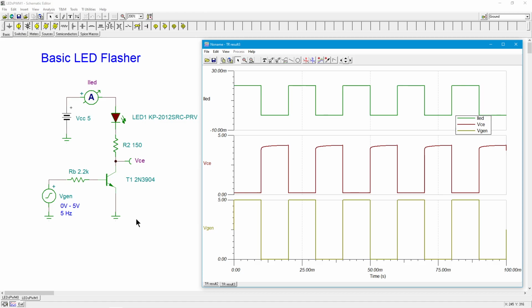on a proto board. Now, when it comes to a motor, if you had a little DC motor, you can whip out this and put in one of those little 9-volt hobby motors that are about the size of your thumb. If you do that, the speed of the motor will change. So when you have a big percentage duty cycle here, you're going to have fast rotation. And when you drop it down, as you go 50, 40, 30, 20%, it's going to start slowing down.